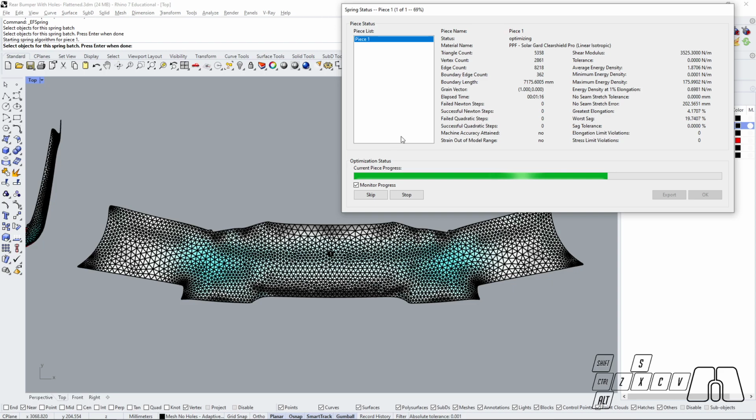Another thing that's important to consider is that over here, it's likely for us to need a relief cut because we are going to have some sag in some areas because of the double curvature that we had there at that area. So this color coding that ExactFlat is showing us will tell us whether we might be expecting to have any kind of strain.